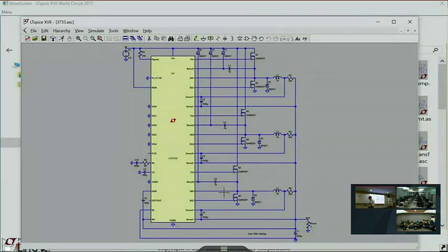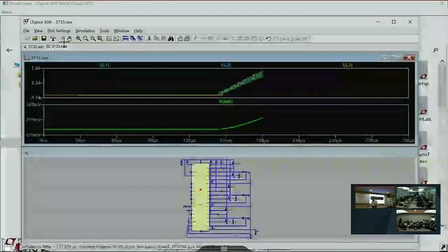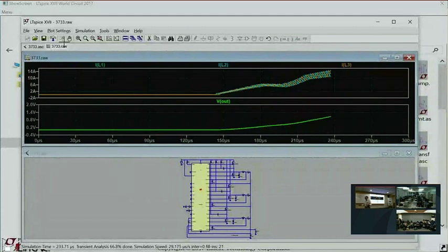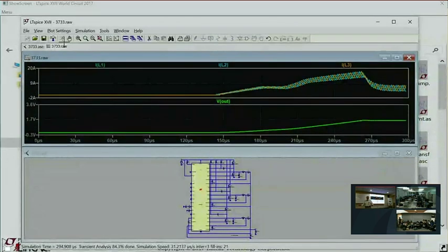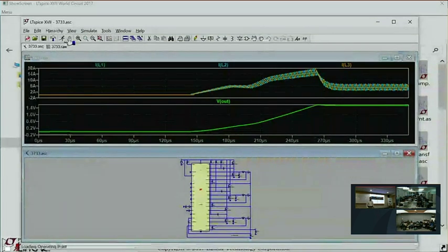What I'm getting at is that this is just a lot of stuff to hook up before you can do your very first startup transient analysis. And you know how these things are. You get one wire in the wrong place, the whole thing doesn't work, and it doesn't tell you why it doesn't work. So that's the value of the jig circuit. You can open up the jig circuit, poke the run button, immediately do a startup transient analysis, look at those waveforms, and decide whether or not you want to spend any more time with that controller or not. That's what they will do for you.